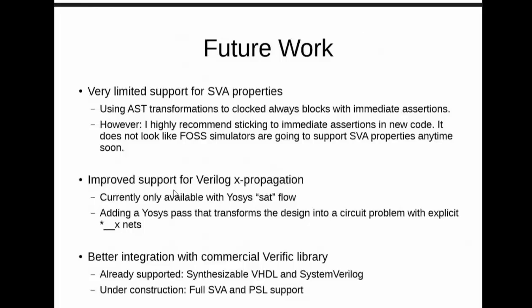Right now already, if you have a license of Verific, you can take Yosys and link it against Verific and then use their SystemVerilog frontend and HDL frontend. But even there, I only have very limited support of SVA properties and only very limited support of PSL properties. This is something that I would like to extend in the future.